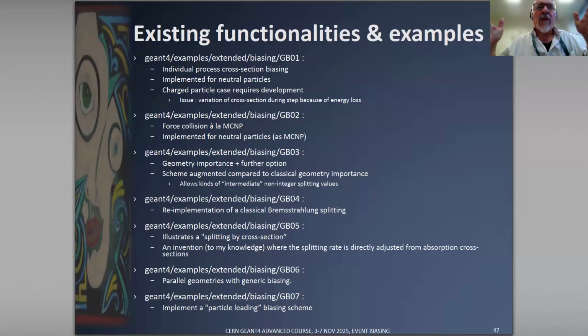If you have to insert slices inside the complicated geometry, this is very complicated. So the aim of the parallel geometry is that you define a geometry which has the same dimension as your tracking geometry, and inside this geometry you define a volume which overlaps with your tracking geometry and which defines the slices.